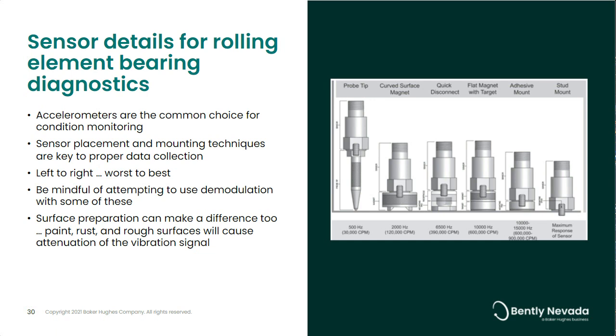It's important when discussing the use of accelerometers for diagnostics that we pay very close attention to the placement and mounting techniques used for these types of sensors. This is because accelerometers are designed to be able to accurately measure amplitudes out to a particular frequency. In the image on this slide, mounting techniques are shown, worst to best, from left to right. As we move from left to right, we see the highest dependable frequency increased until we reach the stud-mounted approach, which yields the maximum frequency response of the sensor.